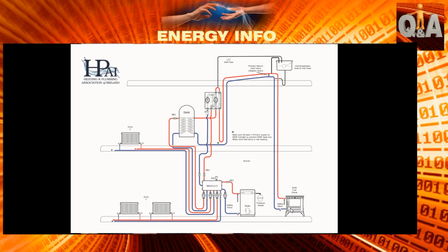So notwithstanding the fact that it's going up and down, the cylinder and the energy link and everything is up above the stove. And just as with a hot water cylinder, if you heat water with the stove, it wants to rise up. The only reason it will want to come down is because the heat has been stripped off, it's heavier, and it finds a path to come down. The path in this instance is from the cylinder coil up around and up on the return across the attic. It vents again on that little half-inch valve, so that you have no airlock at that point, and drops down into the stove. And again, the cold feed is on the last. Yeah. Very good.